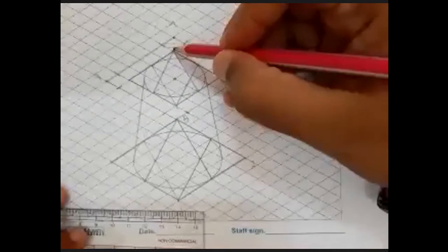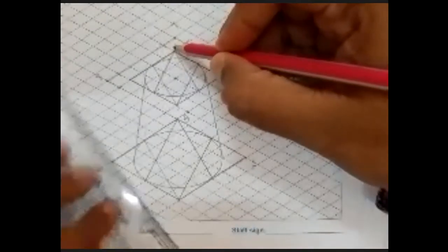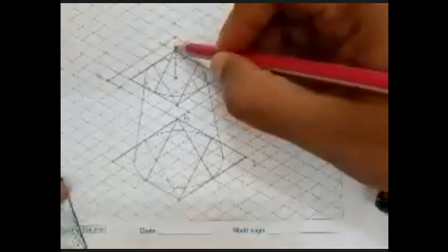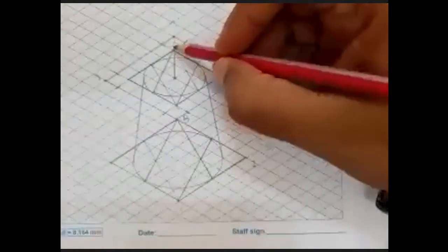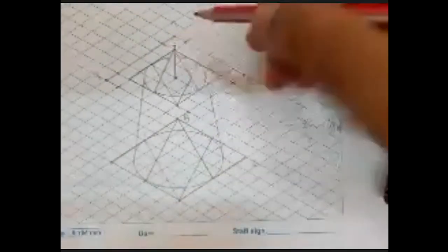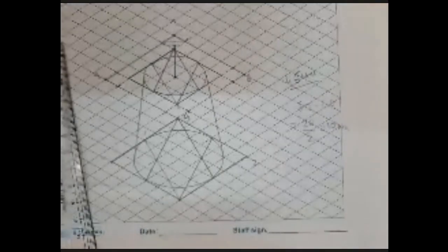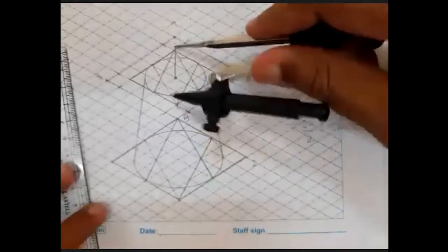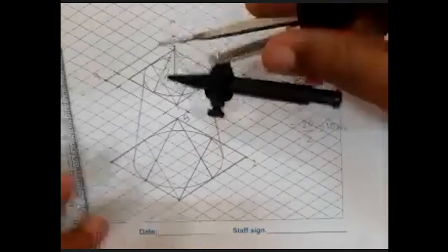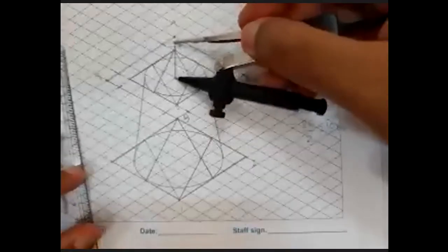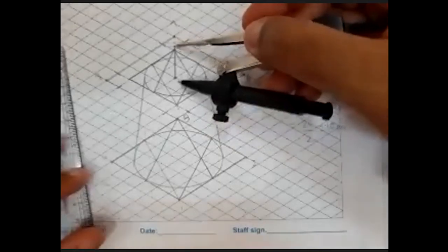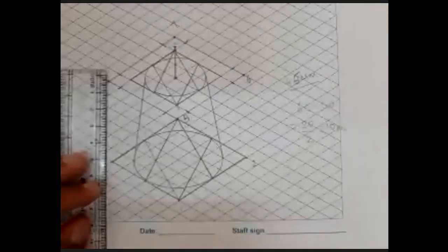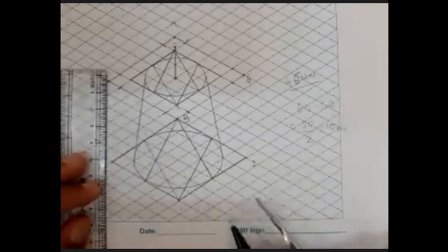Half of that will give me 22.5. So what I do is I just count the number of blocks with the isometric projection. Whatever I have got is 22.5. Then for the sphere circle, I'm not going to measure the radius here. This is the length in isometric scale, but a sphere will always look like a sphere, whether it is in isometric scale or in a 2D drawing.